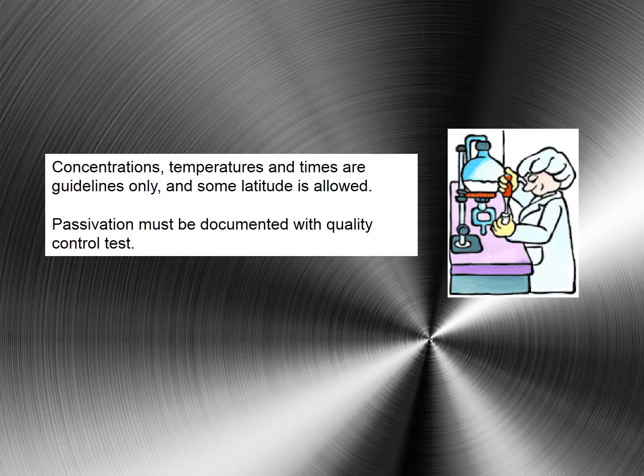If you decide to go with any of these formulations, you must know that temperatures, times, even concentrations are only guidelines, are not mandatory, and in order to document that you achieved the passivation, you must include a quality control test.